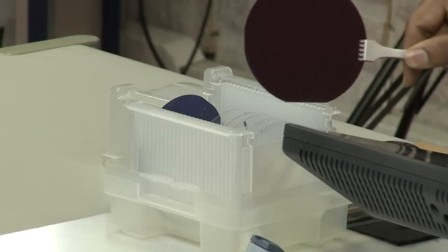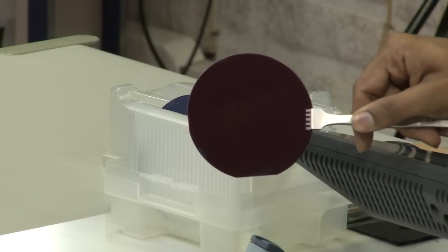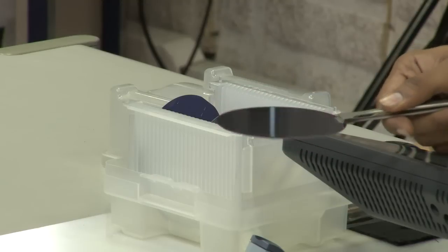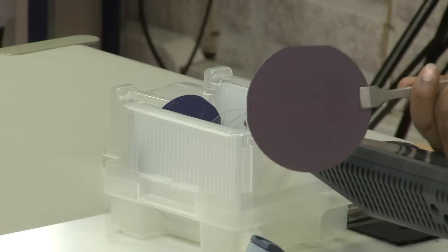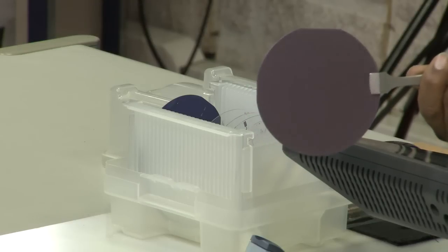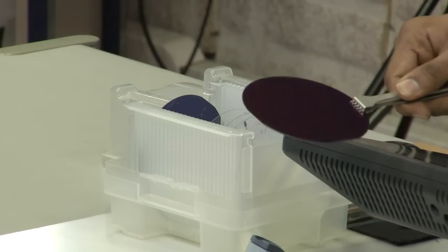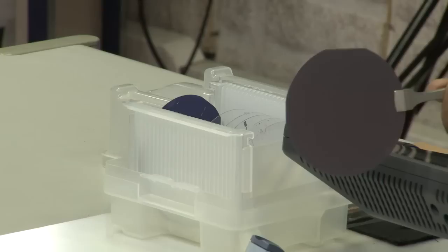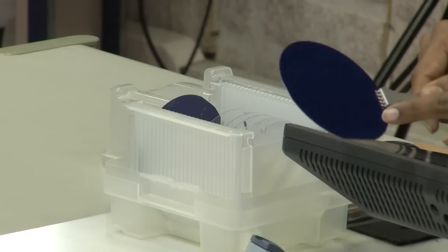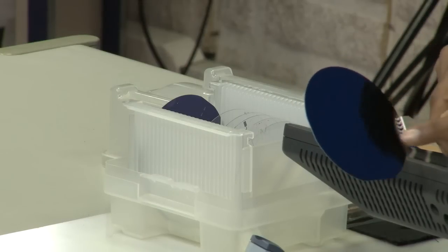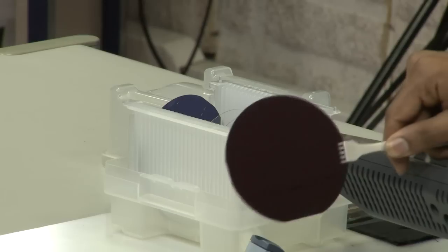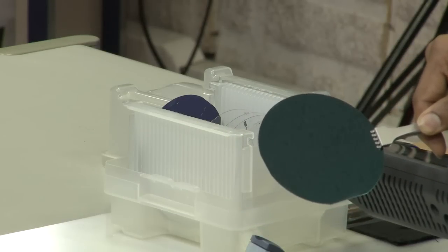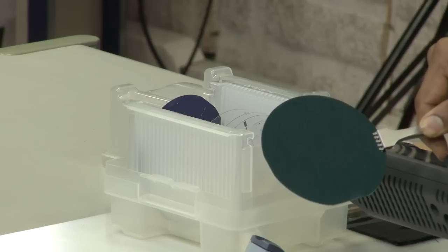What you see is a 4-inch wafer in my hand, and you see on the back side, this is a single side polished wafer. That means one side is polished, this is the polished side, and this is the unpolished side, alright. And on that I have grown 1 micron of silicon dioxide, you can see the greenish color, right. This is 1 micron silicon dioxide.